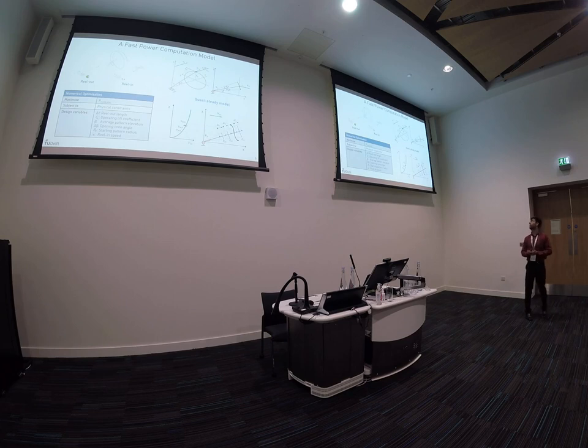So we are developing a fast-to-compute model for this. It's basically a quasi-steady model in which we discretize the reel-out length into a number of length elements, and we assign each length element a single steady state, eventually leading to a quasi-steady simulation. This tries to capture the critical physical aspects during the operation of the ground-gen system, so reel-out, reel-in, and the physical aspects of centripetal acceleration, gravity, etc.